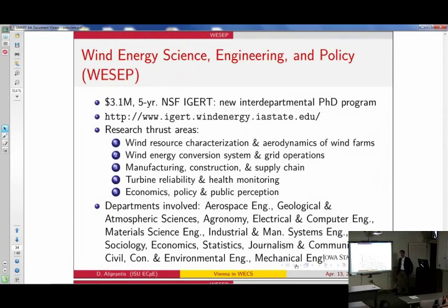Yes, sir. A lot of the commercial IGBTs have a flyback diode already built into the IGBT module. So in your case, were you using IGBTs with a separate flyback diode? I think in our prototype, because that's the thing you can buy, we were using it, but the topology itself, I think, never uses that diode. It's never used. Okay. So you were essentially doing it with discrete diodes around your...